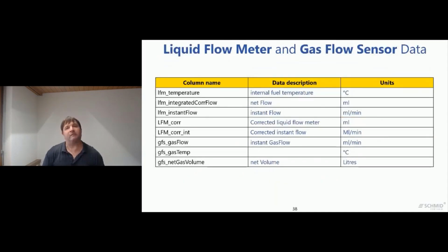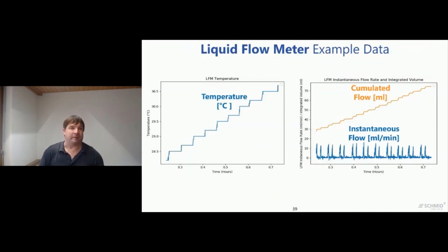Liquid flow meter, gas flow sensor. Here we also measure the temperature. So that means if the car goes out to the track, the engine compartment gets hot, temperature rises, and then we need this temperature to kind of compensate in the smart sensor itself.